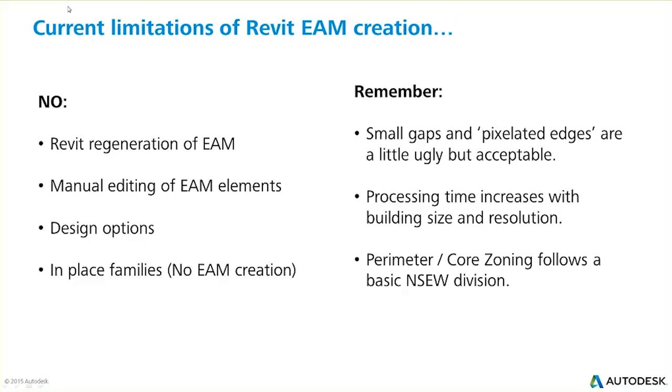Also remember, you'll notice in some of these models that energy modelers have always talked about creating a clean or airtight model. That's very often been driven by the understanding of the third-party tool requiring a model like that. But in reality, all energy simulations, whether they're DOE-2, EnergyPlus, IES, and so on, do not require a closed shell model. What's important is representation of areas and orientation and so on.